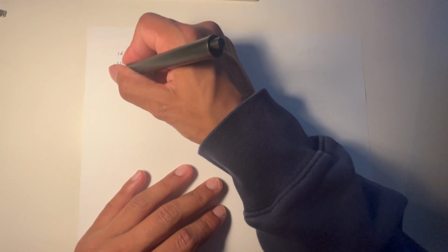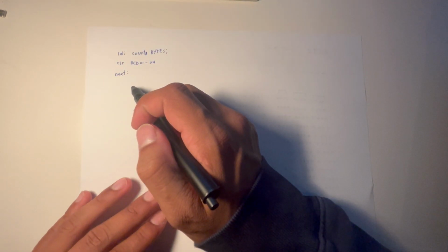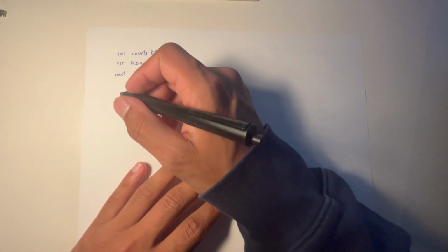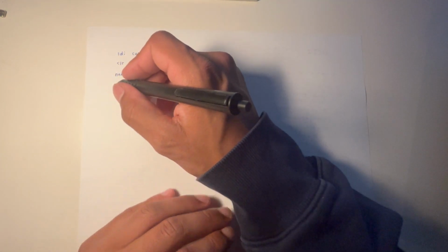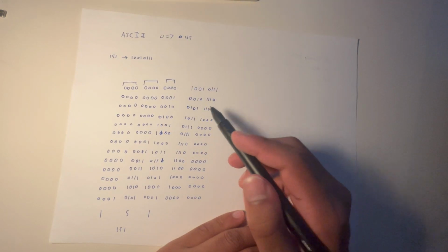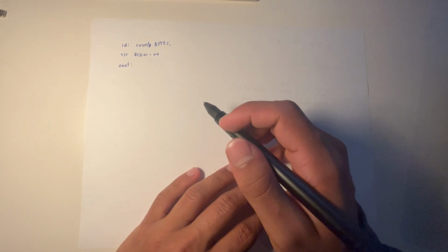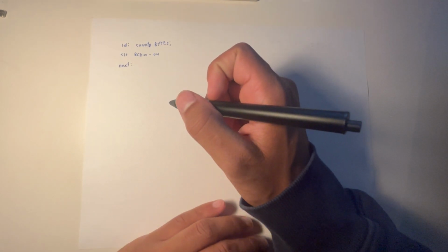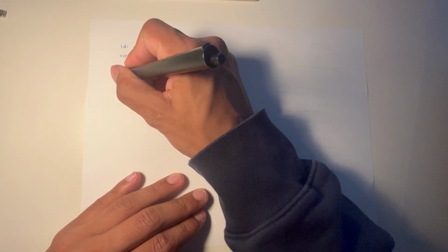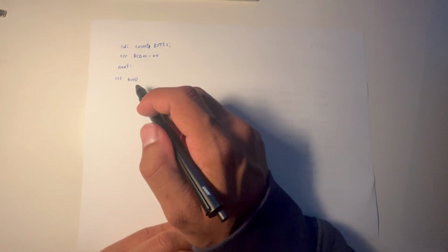So now we have a label called next, and this is where the program counter is going to jump to every iteration. So on each iteration, the first thing we're going to do is shift left. To do that, going back to our pen and paper, each byte is a register. So since we have to get each register to overflow into each other, we can use the rotate function. And the rotate function essentially takes, rather than bringing a 0 in from the right, it takes whatever was in the carry.